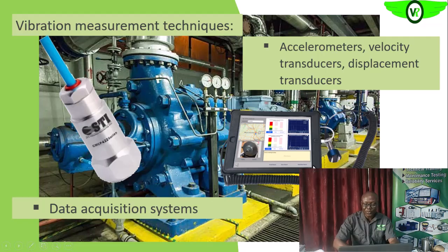So as you collect your information by pressing whatever button you have on the analyzer to collect data, you can also be looking at the live data, looking at the vibration as you are measuring it, looking at the waveform and also the spectrum. And you will see them live as it's changing with time.